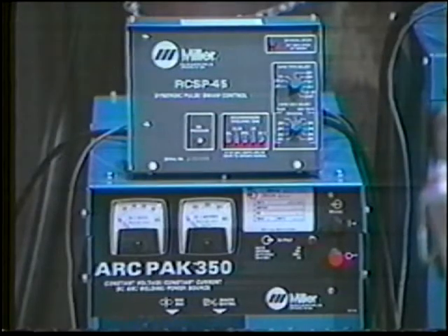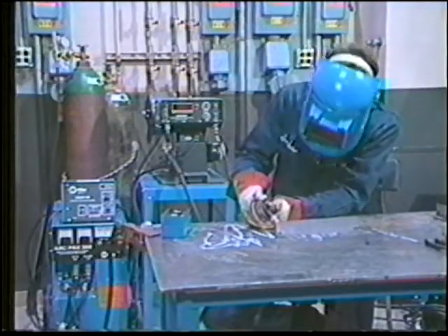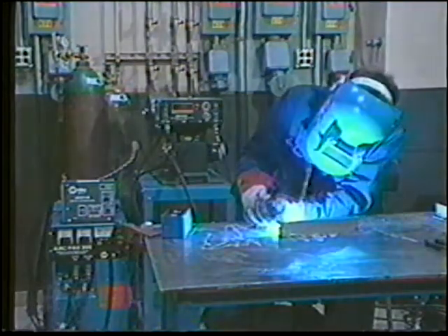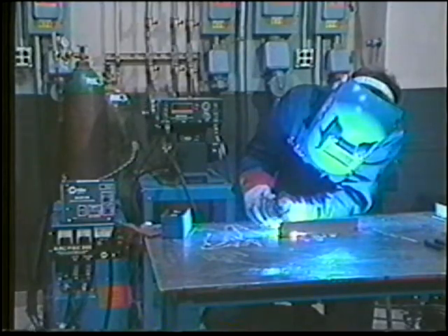The power sources or pulsing accessories used for pulse spray are especially designed for the process. Either 60 or 120 pulses per second can be selected at the front panel. When in the standard position, the output is not pulsed. With inverter-type machines, the frequency is often variable, not fixed at the specific pulse frequency. The wire feeder and gun are the same as used in other gas metal arc applications.